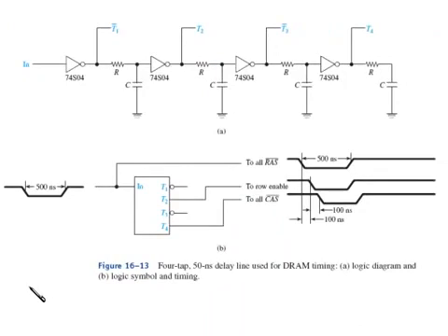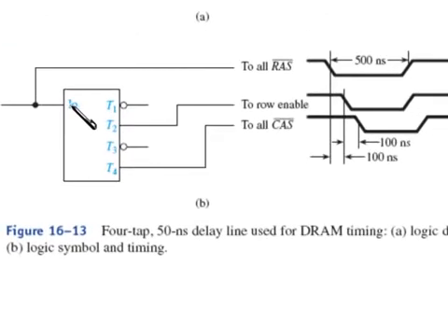So to get these precise timing waveforms, they do have delay chips, so you can come in with a single pulse and have multiple taps on the output. And this is set up as a 50 nanosecond delay line. So when the input signal comes in, 50 nanoseconds later on T2, you'll get the exact same duplicate signal, but skewed over by 50 nanoseconds.